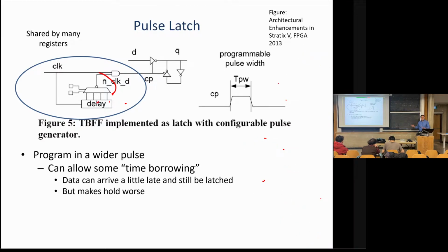Does everybody understand that? One of my favorite questions on a PhD qual is I actually give people a circuit where I have setup and hold violations to see if they can analyze it. Many of our students actually do not fundamentally understand how setup and hold works, but that is how it works. Setup is you must get there in 1 clock period, and hold is you must not get there in 0 clock periods. That's the fundamental meaning of them.